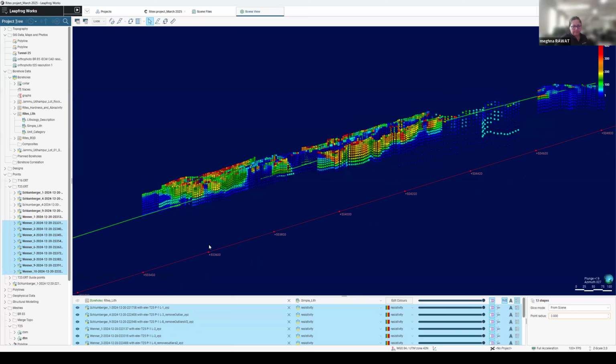Different litho units are interpreted based on the resistivity values. Based on the final geophysical report provided by RITES, low range values correspond to highly saturated free flow zones or clayey material. Intermediate resistivity values correspond to highly saturated weathered zone. Higher range values correspond to unsaturated zones intermixed with rock. So that was the interpretation from the report.